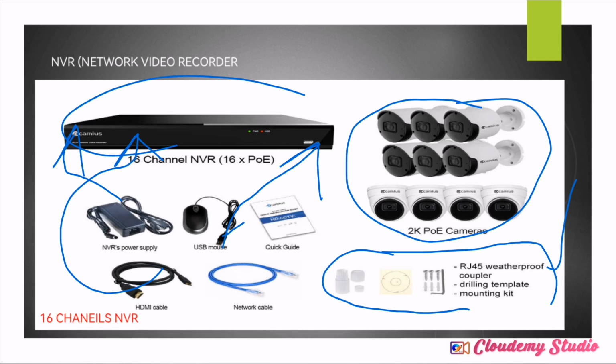So these are something that we use to cover the network cable, in order for water not to enter inside the network cable, because once water enters inside the network cable, then you're going to have a challenge with signaling or sending the data to the MVR. So that's the reason why you need the weatherproof. It's just a box where you cover it nicely, to prevent water during rain season from entering through the box and damaging the network cable.